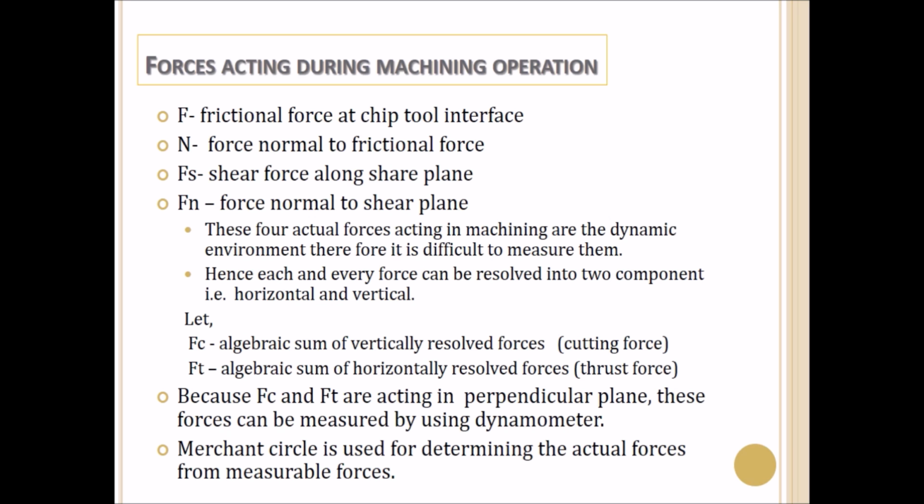So there are four forces: the frictional force at the chip tool interface, denoted by F, and the normal component to that force, denoted by N, and the shear force along the shear plane and the normal force to the shear plane. These four actual forces are generated in a dynamic environment, so it is difficult to calculate them. So in order to measure the four forces,